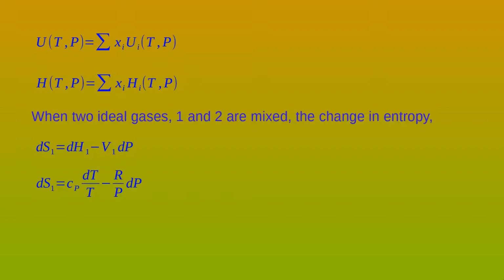Now, the internal energy of oxygen is going to be 2 into 20 multiplied by 25 minus 0, where 0 is the reference temperature. Now 2 into 25 makes it 50, and 50 into 20 makes it 1000. Similarly, 1000 will also be the internal energy of nitrogen.